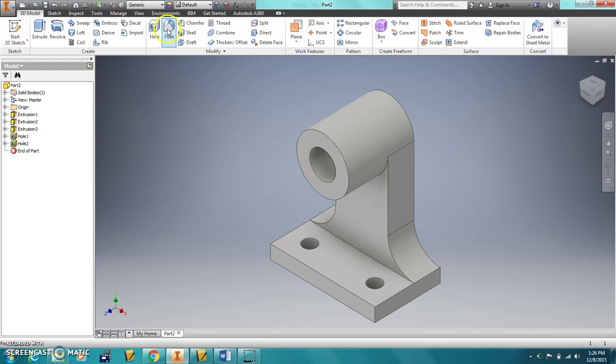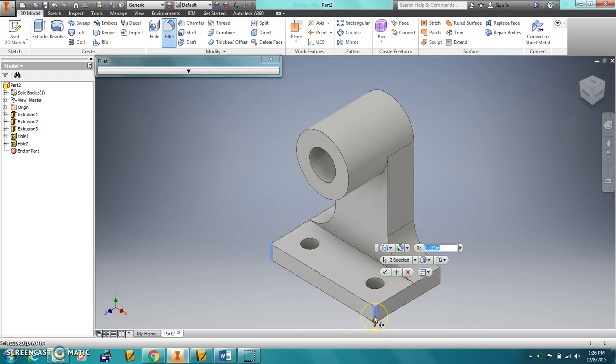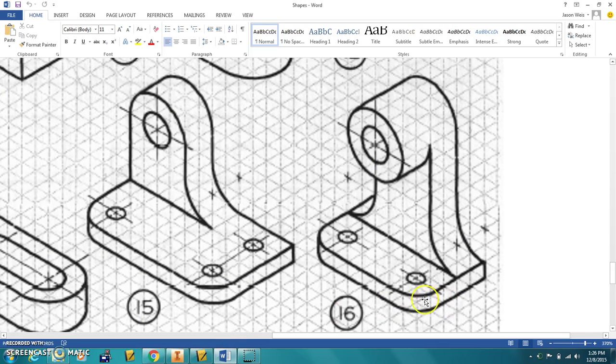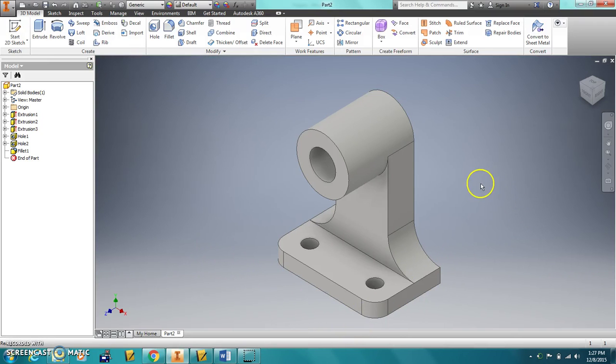So there, we're just going to use the fillet tool. Click on both edges. I'm looking at the diagram. Looks like that front rounded edge has a radius of 1, so that's where the curve starts. Okay, to where if I extend both of those points, it has 1 cube distance. So it's going to have a radius of 1. So I'm going to type in my radius is 1. And there I've got my rounded edges. And there you have part number 16.